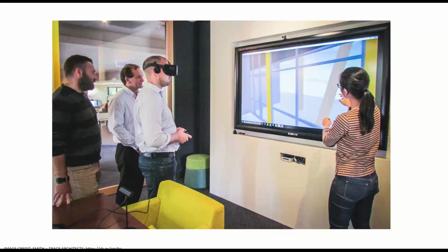And I also think it's really interesting to look at the other avenues of exploration that cross reality allows us to spin up. So we can highlight other pieces of design intelligence as well. In addition to exploring the immersive space, we can layer on information or analysis from the design directly onto the experience. For example, we can expose wall finish data while coordinating with our interiors team. We could layer on spatial daylight autonomy information when coordinating with sustainability consultants. Or maybe we could even expose construction costs and really just allow the client and the team to quantify the impacts of design decisions as they're making them, rather than relying on a long feedback loop, which inevitably ends in a value engineering exercise.